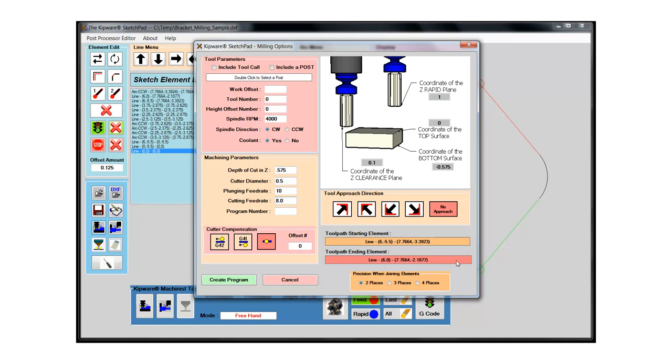So what I want to do is I am programming off the part. And so the center line of the tool would be riding in here, and obviously it would be too small. So I'm going to use the cutter comp offset in the machine to give me an opportunity to cut the part, but yet have the offset ability to bring the size of the part into play. So I'm going to use G42 because this is the direction that the cutter is going to be moving, and I'm going to use offset number 30 at the machine.